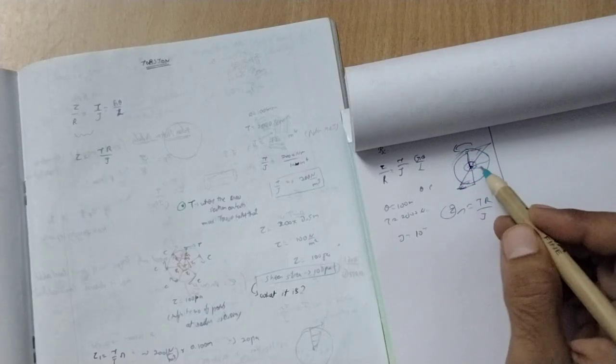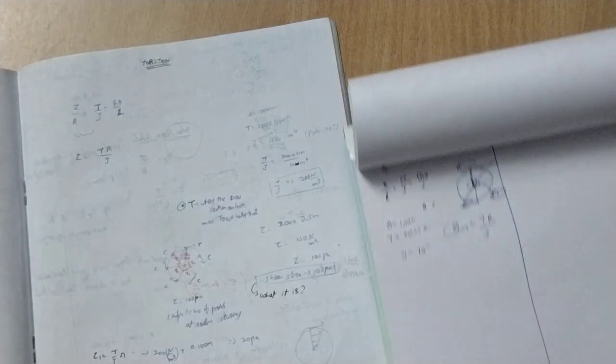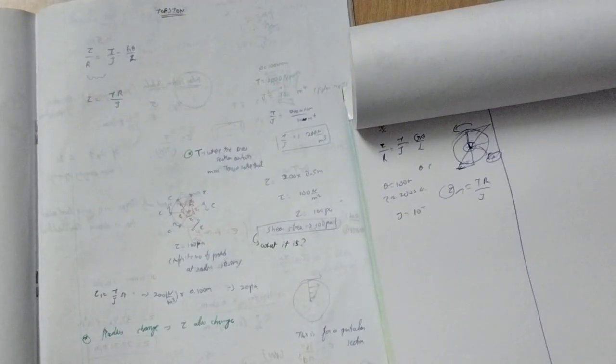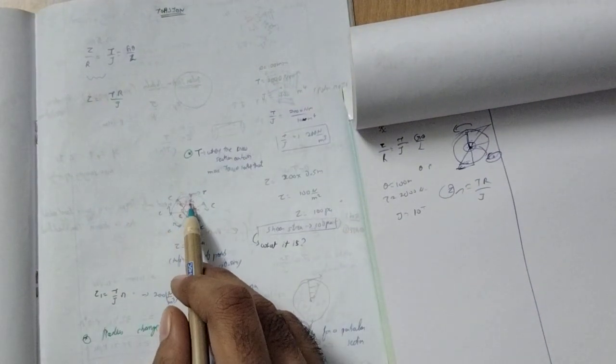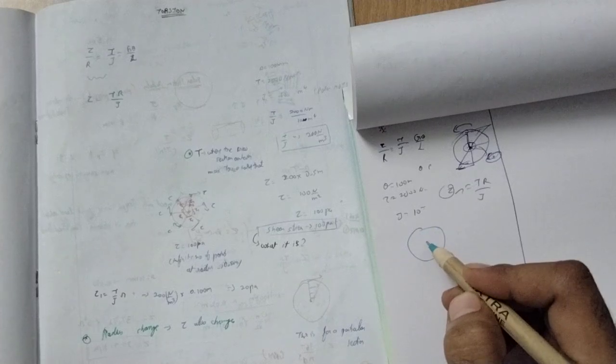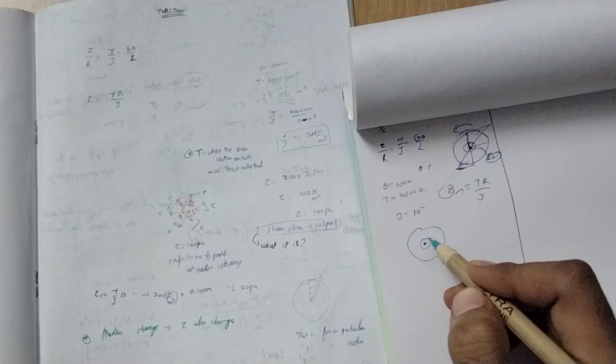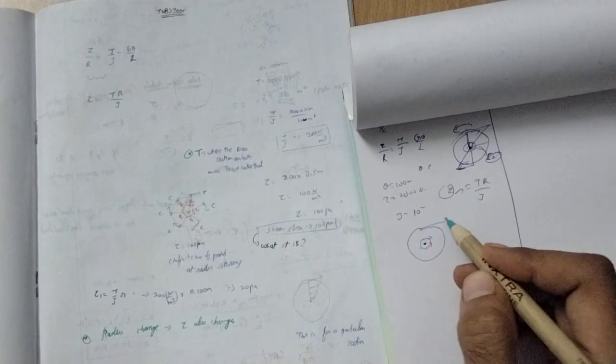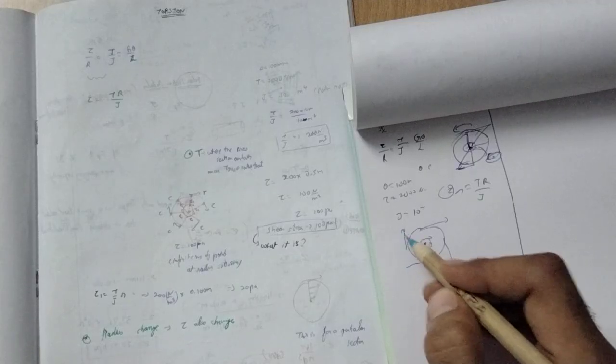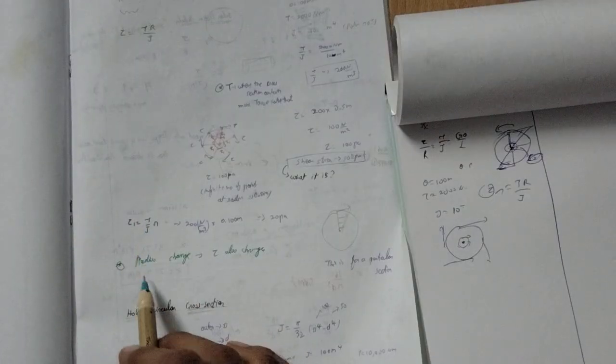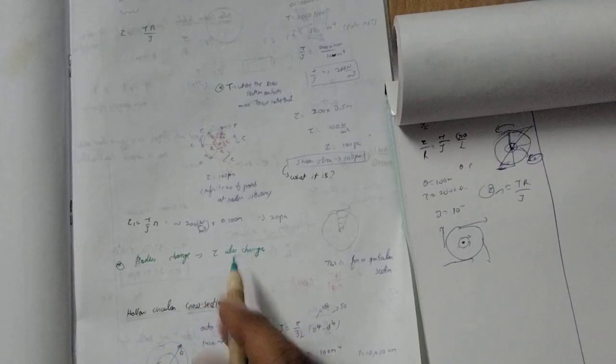So here you can see the shear stress is 0, tau equal to 0. The entire thing like this will be shear stress 0, and while it moves outward the shear stress increases little by little, and becomes maximum at the outer surface. So just a simple thing. Tau by r equal to T by J is the basic formula, and along the radius the shear stress also changes.